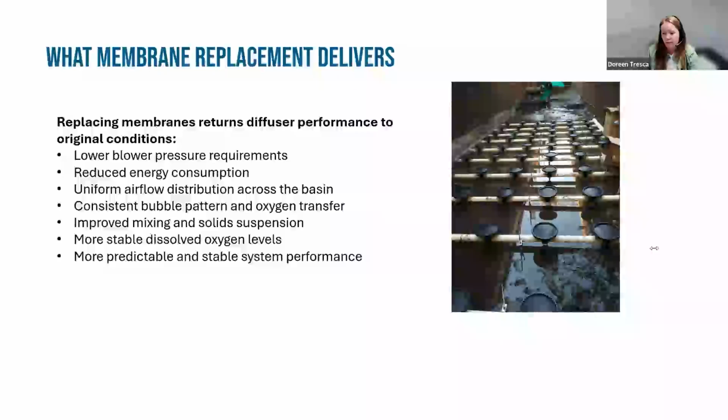You also are going to regain uniform airflow distribution across the basin. So any of those dead spots you saw, any of those over aerated spots you saw, by replacing the membranes, you're going to fix that issue, and it's going to restore consistent bubble patterns and oxygen transfer. Again, it's going to restore it back to the way that system was designed when you first installed it. The improved airflow is going to help restore mixing, help keep the solids in suspension, and stabilize any DO levels that were uneven across the tank.